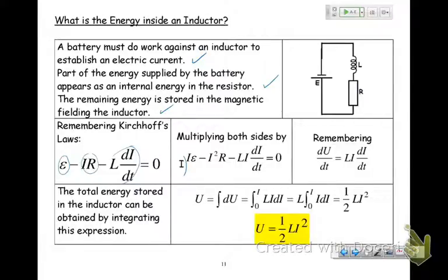It's kind of interesting. What it says is that for any given current, my energy stored in the inductor, so twice as much inductance, twice as much energy. And for a given inductor, my energy scales with the current squared. So if I double the current, I have 4 times the energy stored. I suppose the reason why I don't care that much about it is because we don't tend to use inductors very often for storing energy. We tend to use them for their transient properties.